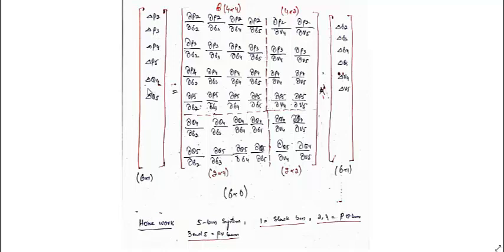are the equations which we have found from the specified values of the real power, because real powers will be specified on all the buses except the slack bus. That's why here they started from delta P2. Similarly, reactive power will be specified for a PQ bus. Since the PQ buses are 4 and 5, it will be delta Q4 and delta Q5. And the variables here are delta 2, delta 3, delta 4, delta 5.